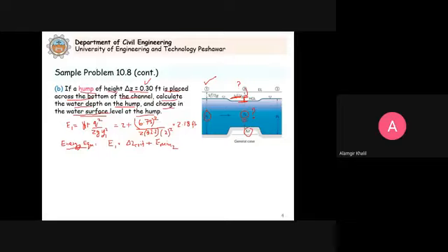Now this E minimum 2 we can easily calculate because we already calculated the critical depth. This will be equal to 3 by 2 times YC, and YC we have already calculated, so you put the values. The critical depth was 1.123, as we calculated in the first part of this problem. So this comes out to be 1.684. This is the minimum specific energy, 1.684 feet.